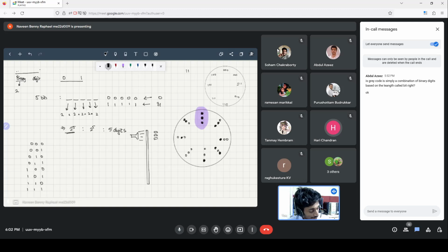Naturally, if you're using gray code in real life, we'll have many more bits. And secondly, the holes won't exactly be like this. The holes will be like solid 1/8 of the wheel, quite big, so that we'll always have light no matter where we are, instead of just small holes here.